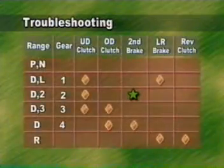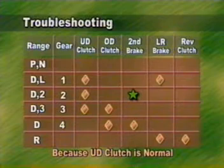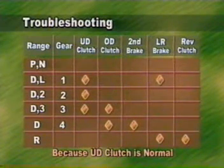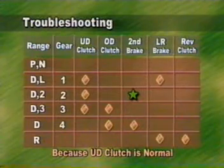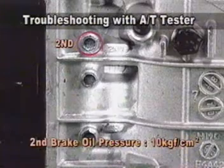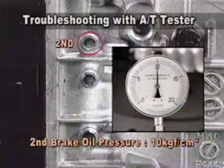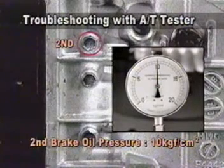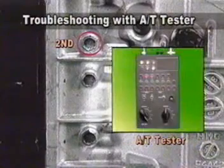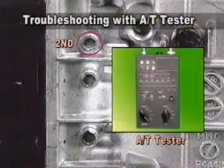If driving is normal in first speed, but troublesome in second speed, second brake is doubtful first of all. If the trouble proves to be not electrical, but mechanical or hydraulic problem, oil pressure measurement of second brake is essential. Auto tester is used to maintain the second speed continuously during the test.